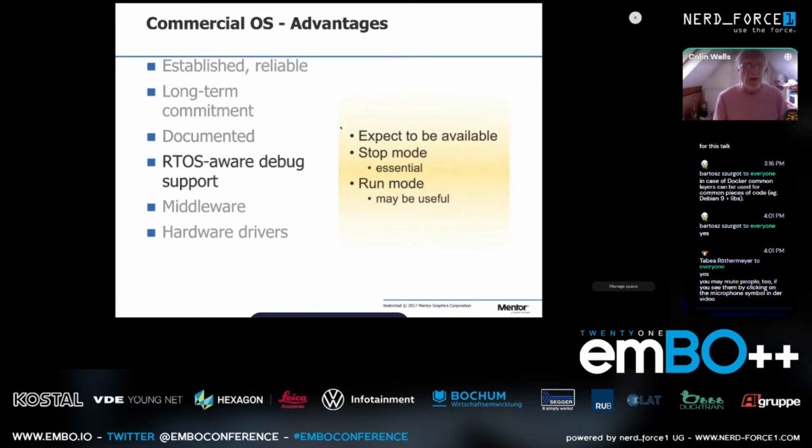You need to have debugging support. Debugging in a multitasking environment requires certain specific kinds of functionality. And the kinds of things you should be looking for is the ability to run in what's called stop mode. That's where you put a breakpoint, probably a task-aware breakpoint somewhere, and when you hit it, everything stops. The other option is run mode, where you hit a breakpoint in a particular task and that task stops, but the rest of the system continues. Neither of these is better or worse than the other. They each have their own places and something you might want to look out for.